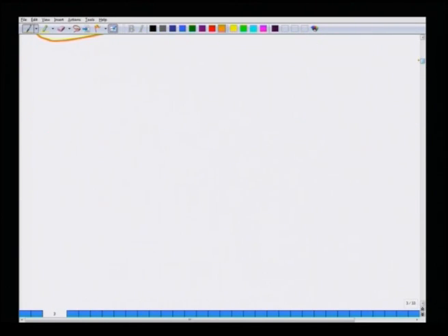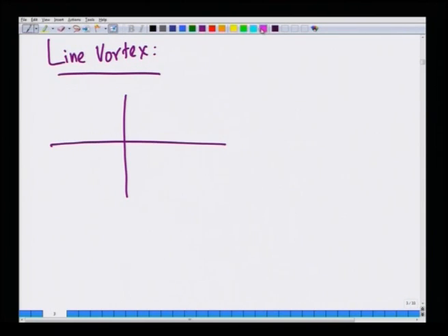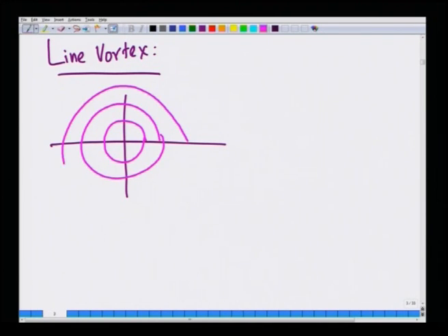We then began to discuss what is called line vortex. Okay, that is the topic that we are going to start now. A line vortex is essentially, if you look at the 2D plane, you have fluid flow completely in circular streamlines. Streamlines are completely circular in the xy plane. So, you have v theta is some constant by r, and v r is 0. Now, this is the description of the velocity field. So, from this you can find out, use cylindrical polar coordinates.